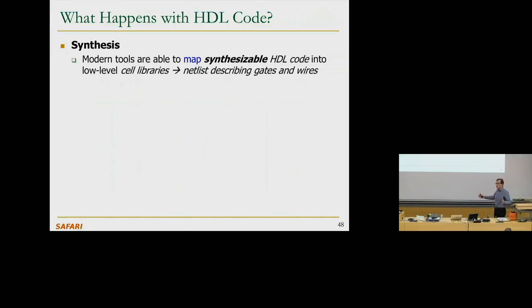Basically, you have modern tools called synthesis tools that are able to map hardware description language code to low-level cell libraries. But not all kinds of hardware description language code. There's a synthesizable portion, and this depends on what kind of tool you use. There are some synthesizable constructs, there are some non-synthesizable constructs. If you do gate-level structural Verilog, everything's synthesizable. Most of behavioral Verilog is also synthesizable. But if you go fancy, it may not be synthesizable, because now your tool needs to actually figure out what kind of low-level circuit it needs to generate based on the description you have, right?